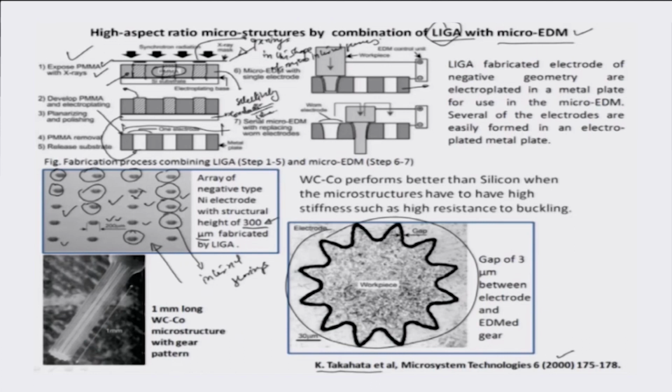Now, the advantage here is that these cavities are already pre-coated with platinum, right. They are platinized and metallic in nature, so they can be made an electrode. Typically, if you want to do EDM operation, this is made the cathode, and the workpiece has a size close to the hole that can be seen here, and the workpiece is made the anode.